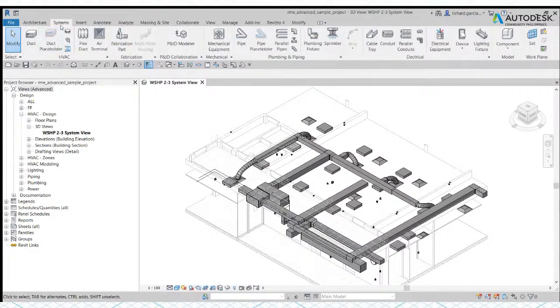dock tool here, you hover your pointer, do not click, just hover, you can see that there's a shortcut, right? The shortcut is DT. If you are using AutoCAD, when you type a shortcut, you also need to press the Enter button. In Revit, all you have to do is type the shortcut, so you don't need to press Enter.